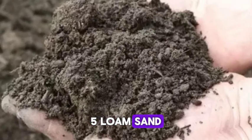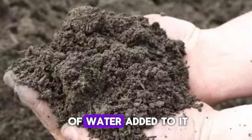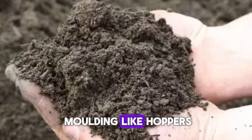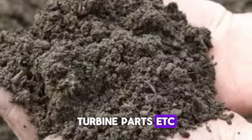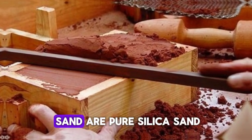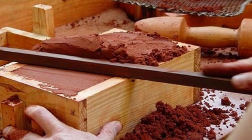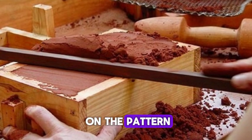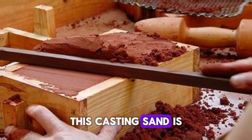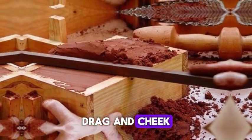5. Loam sand. Loam sand is an equal mixture of sand and clay with a sufficient amount of water added to it. It is also used for large and heavy molding like hoppers, turbine parts, etc. 6. Parting sand. These types of molding sand are pure silica sand poured on the faces of a pattern before molding. Parting sand is sprinkled on the pattern before it is embedded in the molding sand. This casting sand is also sprinkled on the contact surface of cope, drag, and cheek.